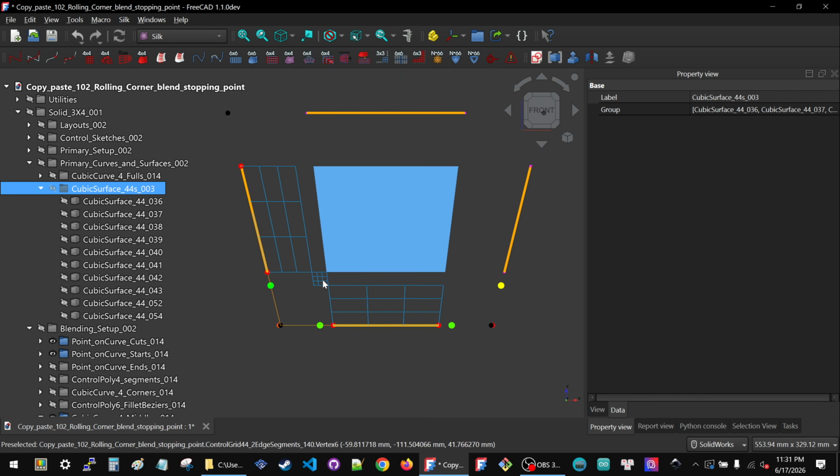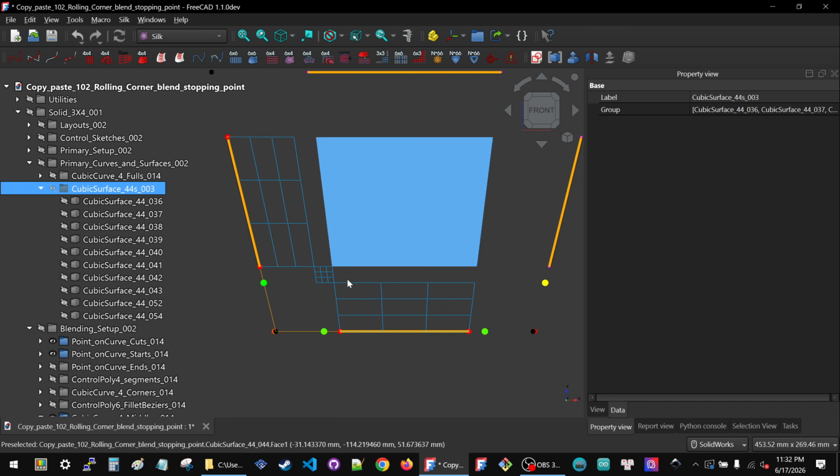And because the rounding is going to consume some space, I have to push back the blend. The edge blend used to be all the way to here, but now it's only going to be here. I don't edit the segment that was used previously to make the blend. I just create a new one in case I want to switch back. And it's just too painful to try to find the old segment grid and to move its reference. So I just make a new one. It makes it backwards compatible, and we don't have to do pointless surgery on something like this. Okay.